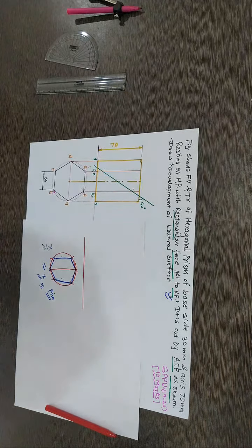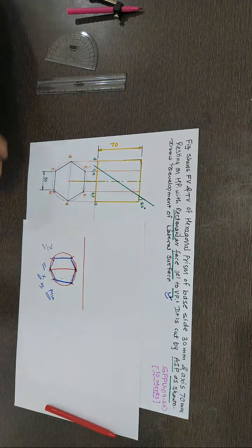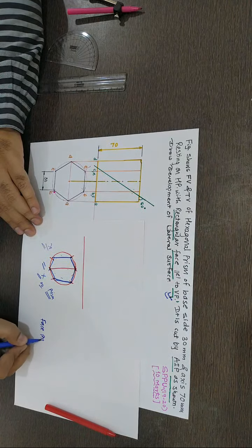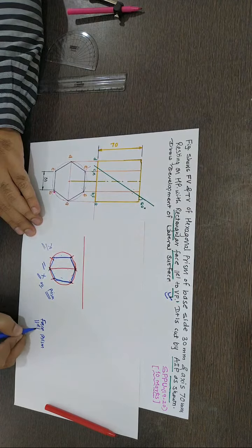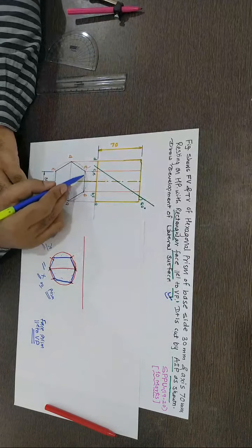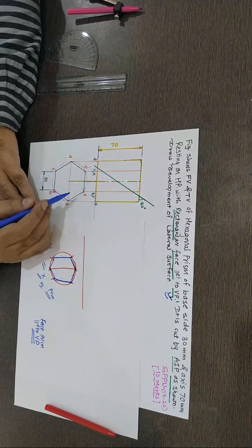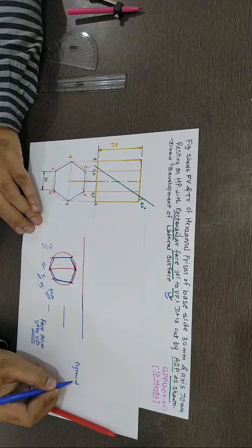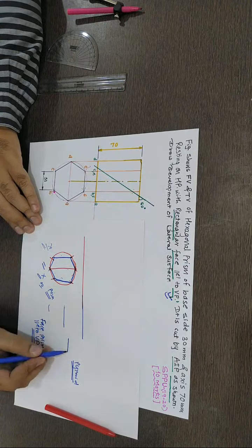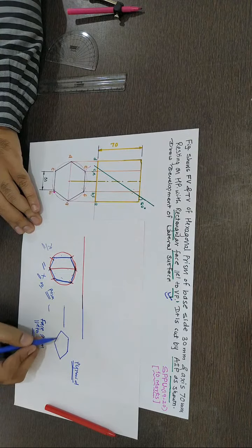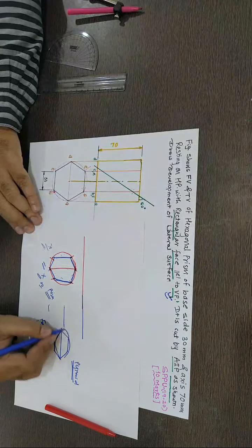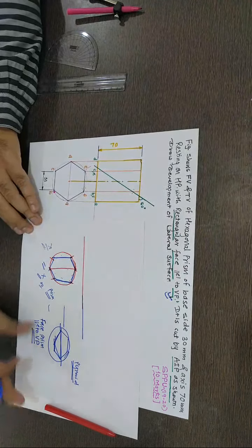Okay, I think it's connected now. So yes, when they have mentioned that one face of a prism is parallel to VP, then for the base edge, in, let's say, a hexagonal prism, we should always draw this position of the hexagon like this, by first drawing a circle and then one horizontal diameter. I'll use another page.